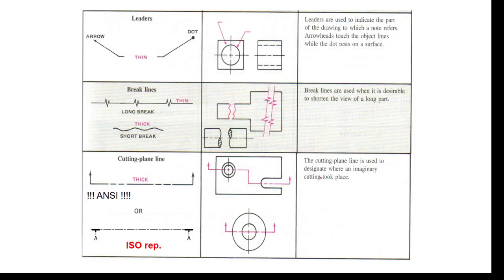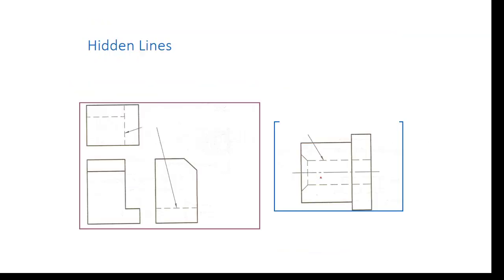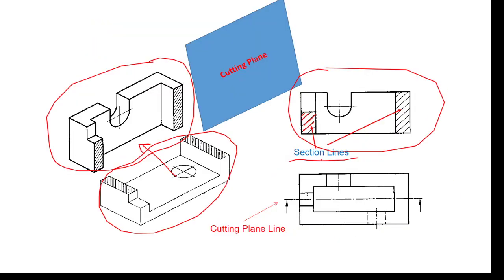It corresponds to the edge of the imaginary cutting plane. It is valuable to inform the reader which cross section has been selected for outputting a sectional view, and at which selected cross section the object is imagined as cut. To answer this question, we draw the edge of the cutting plane.